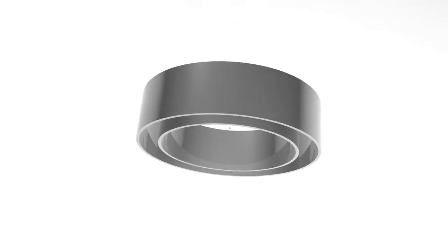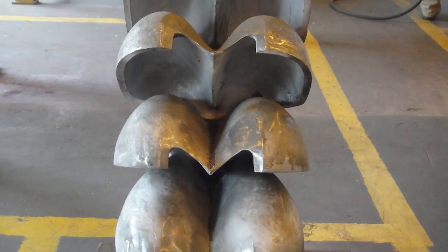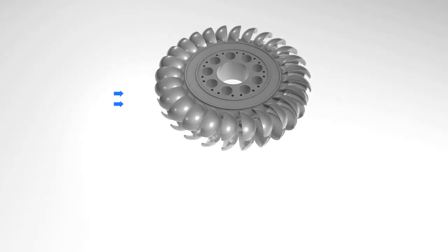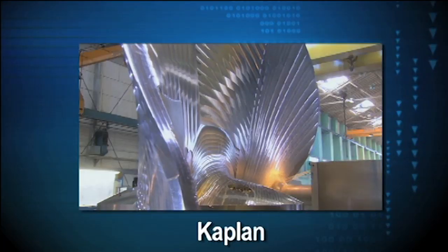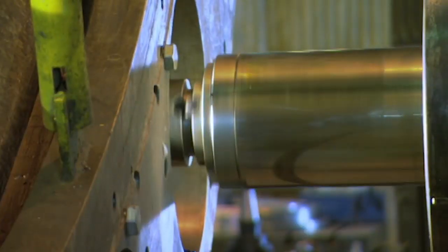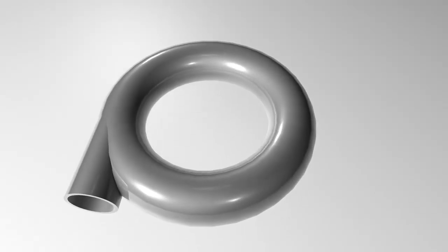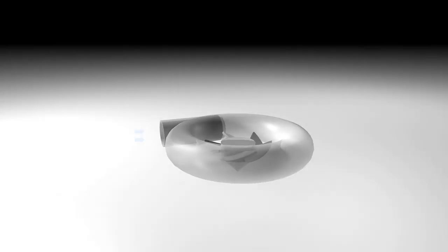Pelton. The Pelton wheel is among the most efficient types of water turbines. Nozzles direct forceful streams of water against a series of spoon-shaped buckets mounted around the edge of the turbine runner, causing it to spin. Kaplan. The Kaplan turbine is a propeller-type water turbine which has adjustable blades. The inlet is a scroll-shaped tube that wraps around the turbine's wicket gate. Water is directed tangentially through the wicket gate and spirals onto a propeller-shaped runner, causing it to spin.